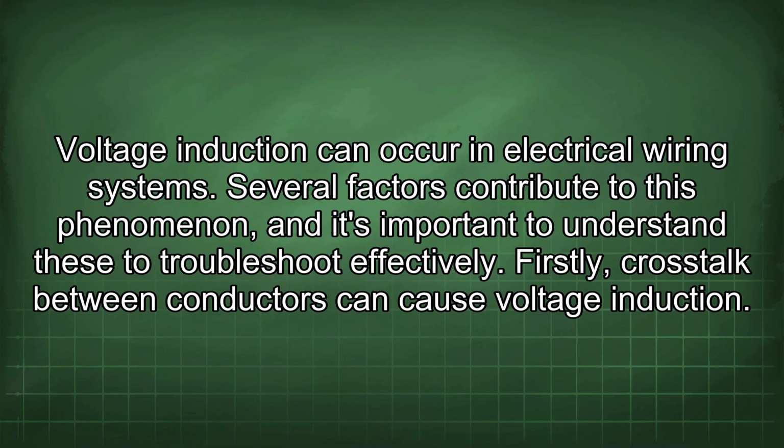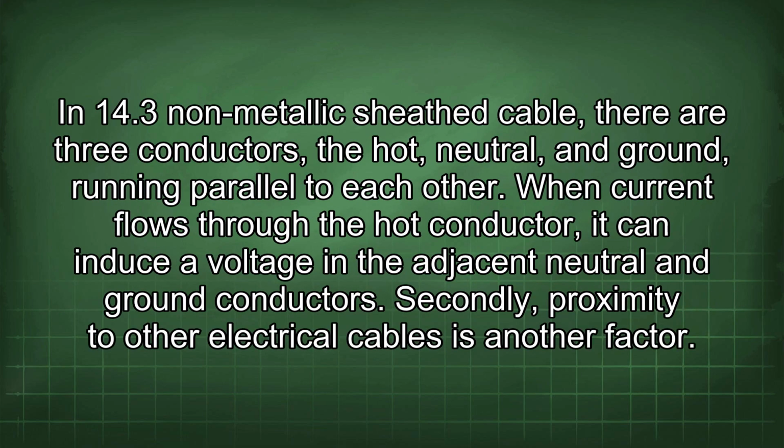Voltage induction can occur in electrical wiring systems. Several factors contribute to this phenomenon, and it's important to understand these to troubleshoot effectively. Firstly, crosstalk between conductors can cause voltage induction. In 14/3 non-metallic sheath cable, there are three conductors, the hot, neutral, and ground, running parallel to each other. When current flows through the hot conductor, it can induce a voltage in the adjacent neutral and ground conductors.